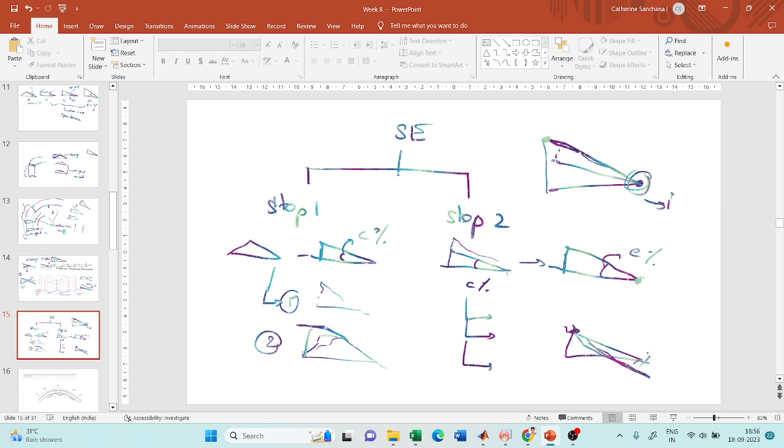So you will remove this portion of the soil which is here. This is rotating about the outer edge. So you add extra material here, and if you're rotating about the outer edge, you have to remove excess material here. Only then will you get the required slope.